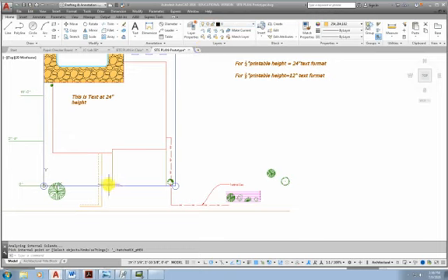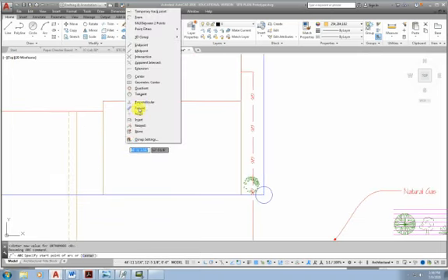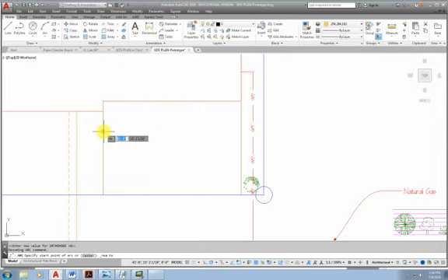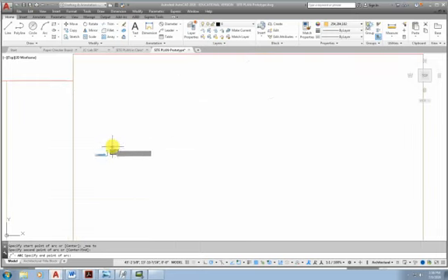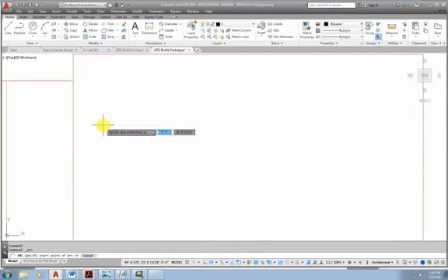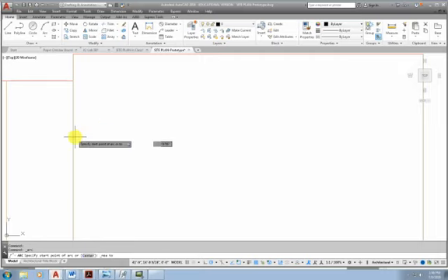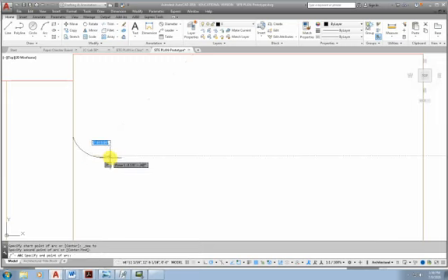For the driveway, we're going to make that set with a herringbone pattern, and I'm going to use this same black, and they kind of scotch this area here, so I'll do the same thing. I'll just get an arc, and I'll use a nearest point to attach that to this line and bring that out. It looks like my colors are overriding, so let's go back to bylayer, 3-point arc, nearest, and then I'll just bring that down.